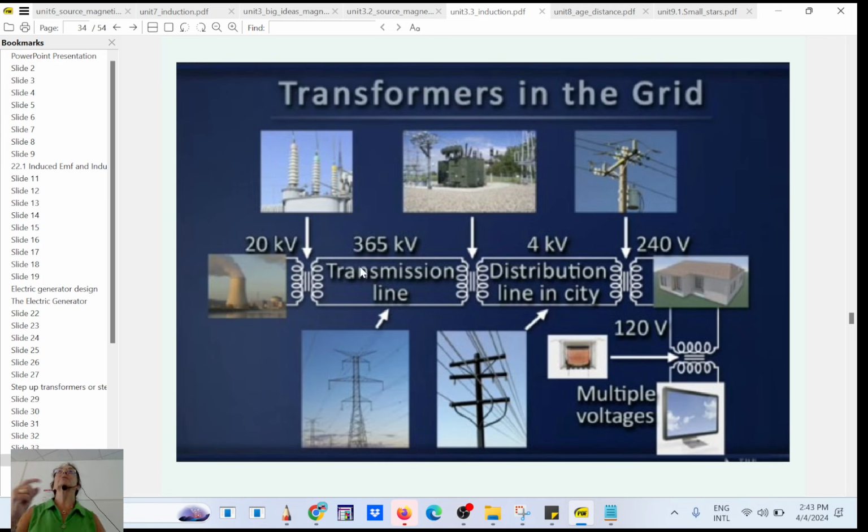So you have to do that through high tension line. And because you don't want to use too much energy because of heat, okay, because the wires have resistance, you need to bring the voltage very, very high. So the current will be very low. So you need to have a step up transformer, about 100,000 volts.